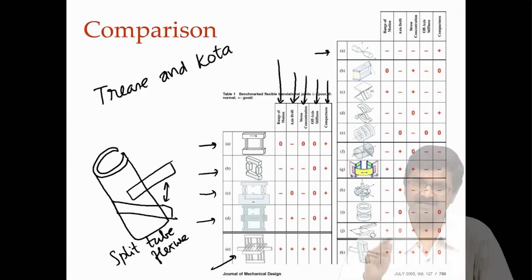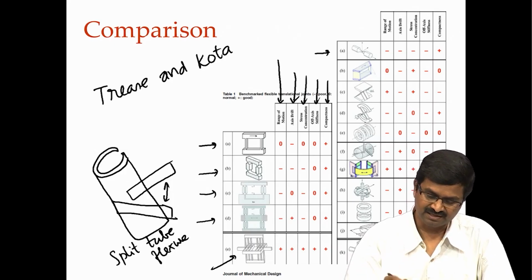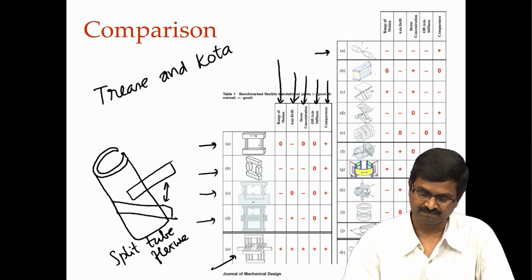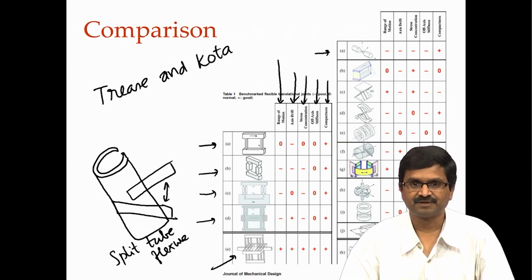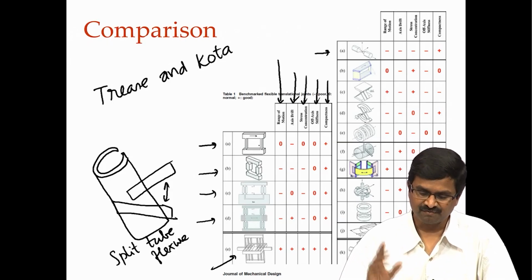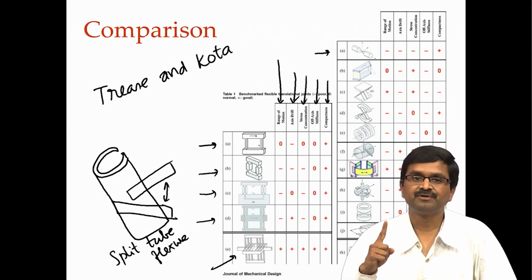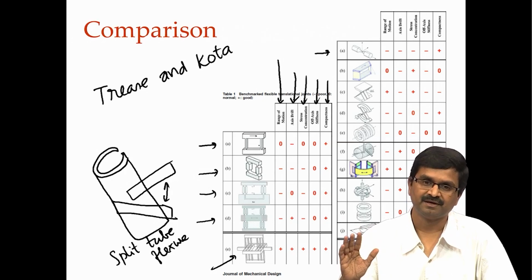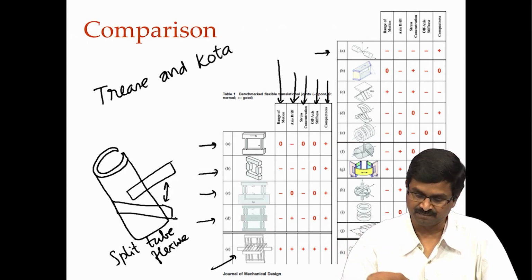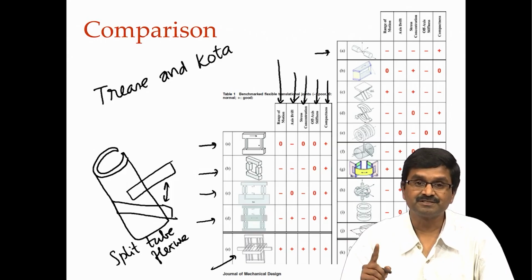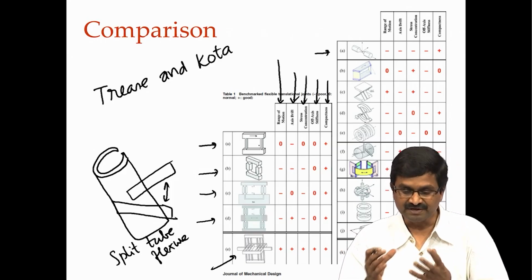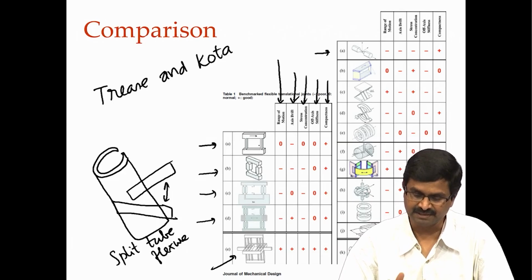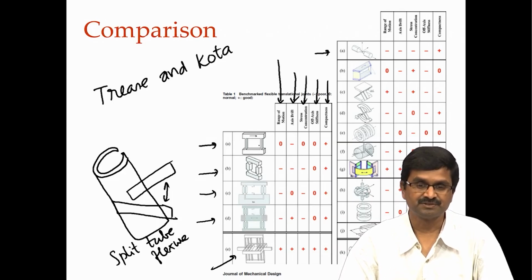One is the range of motion. Range of motion is limited for most of these, unless you use these flexures, even then it is not a whole lot. The other thing they have taken is axis drift, and that is a very important one. These flexures, when they rotate, their axis is not going to remain the same. That I did not mention, that is a very important thing, and modeling that is quite difficult also. All these formulae do not capture it, that is why the errors in them are very high, right, sometimes 20% as we saw, right. Axis drift, and then stress concentration, because they are being heavily stressed in a narrow portion of the material of the compliant mechanism. Stress concentration is very important.